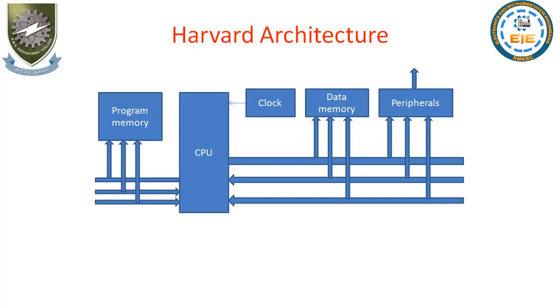Harvard architecture. Harvard architecture physically separates memories for instruction and data, requiring a dedicated bus for each of them. Instruction and operands can therefore be fetched simultaneously. Most DSP processors use a modified Harvard architecture with 2 or 3 memory buses, allowing access to the filter coefficients and input signals in the same cycle.